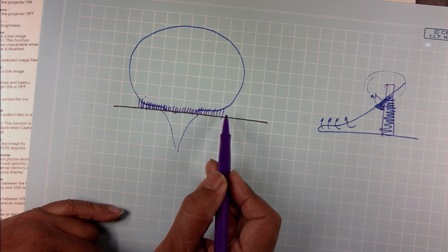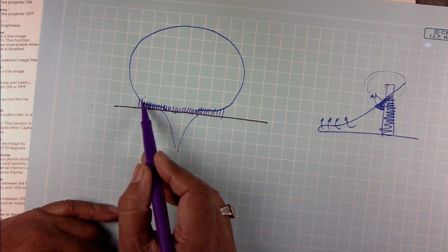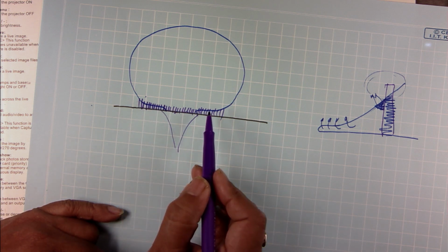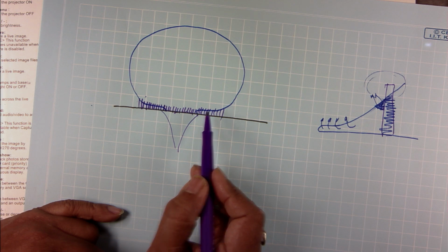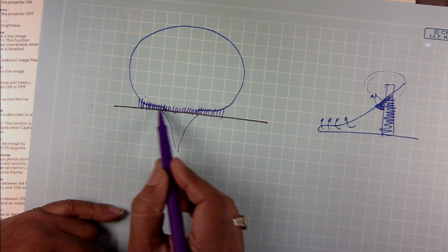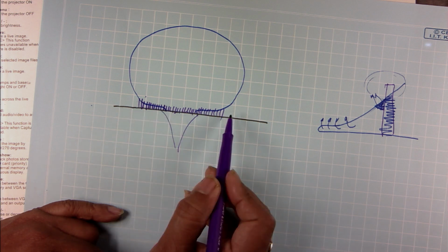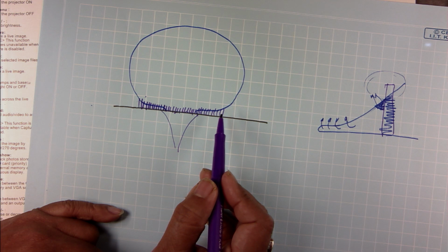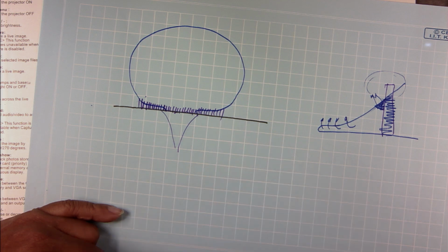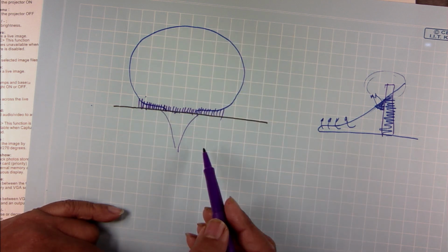And the second part is, if I want to form a bubble in between these nanofins, the amount of superheat that I will need is thermodynamically very prohibitive, because your availability is not going to be that much. The availability that drives the formation of the vapor bubble is much lower compared to the availability of forming a bigger bubble from the cavity.